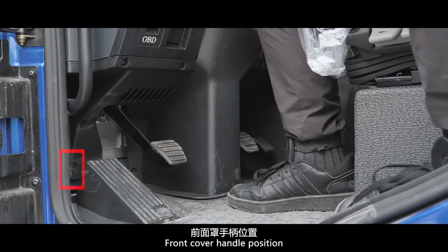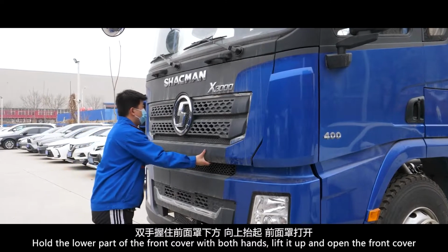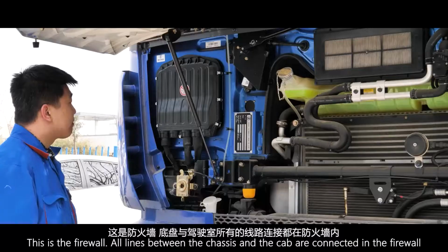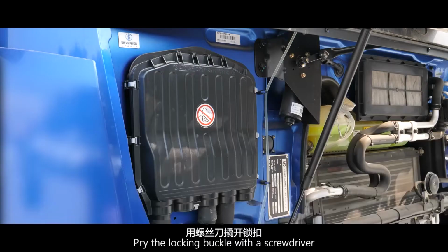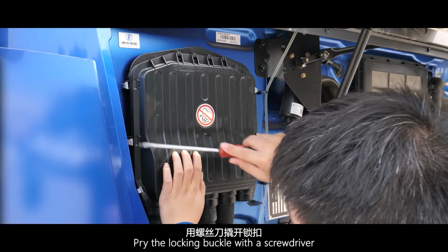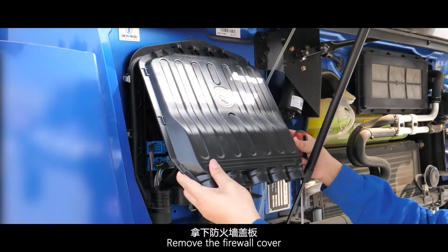Front cover handle position. Pull up the handle of the front cover. Hold the lower part of the front cover with both hands, lift it up, and open the front cover. This is the firewall. All lines between the chassis and the cab are connected in the firewall. Pry the locking buckle with a screwdriver. Remove the firewall cover.